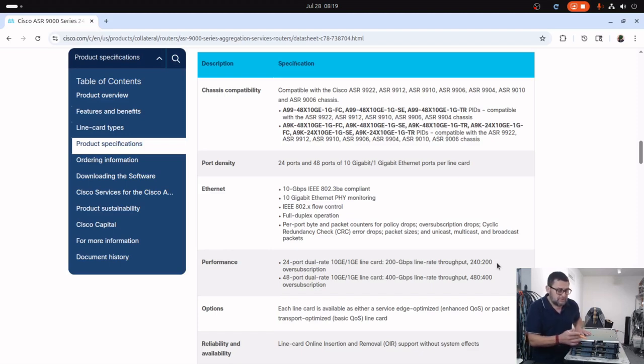So it's very important to check every single connector on the backplane, or the backplane of the chassis, just to make sure that you are not going to insert this line card in a bad slot. So I need to connect this into my chassis and make sure that the operating system recognizes this.